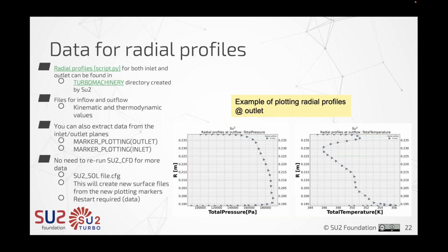The structured ones, there was a case of efficiency in terms of the computational time. Plus, in turbomachinery, the mesh quality is very sensitive. For example, Cadence Pointwise is basically the industry standard, at least in Safran, for generating meshes for fans, turbines, compressors. And it's scripted and automated, and it's basically multi-block.